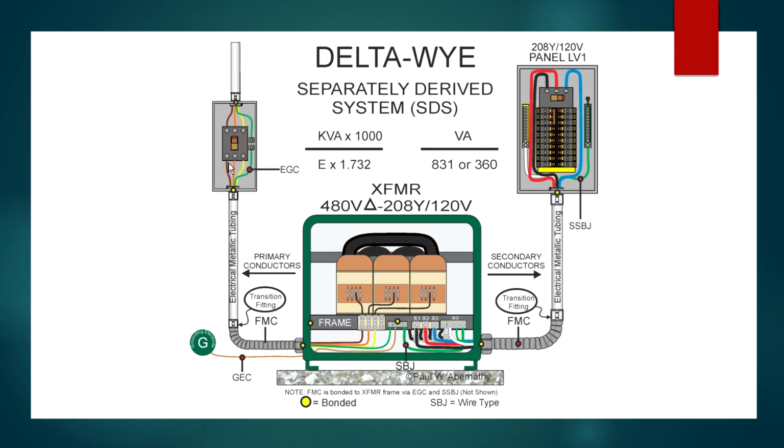So let's take the 90 times 1.25 again, and that's 112.5. So if I size a conductor, and of course we haven't done conductor sizing and that wasn't part of this video, but I'm just trying to show you what we're talking about here. If I size these at 112.5 amperes, let's see if that is okay for it to terminate onto a 125 amp overcurrent protective device. So that takes us back to the code.